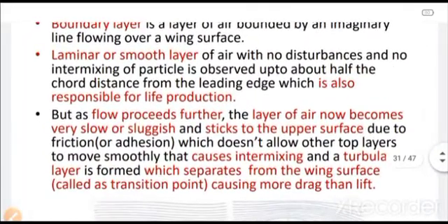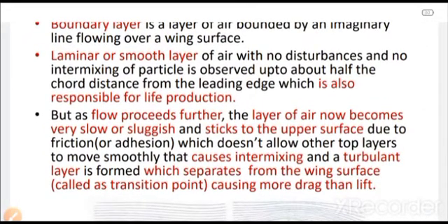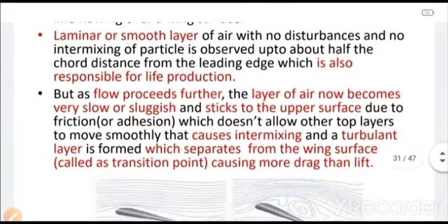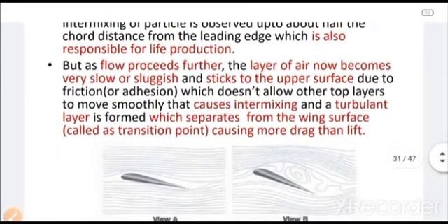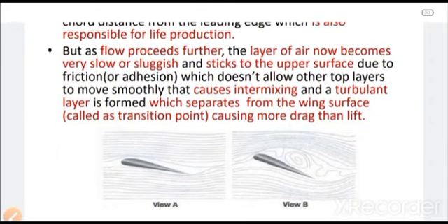so that it does not cause so many disturbances. Laminar or smooth layers of air with no disturbances or intermixing of particles are observed up to about half the chord distance from the leading edge, which is also responsible for lift production. But as the flow proceeds further, the layer of air becomes very slow or sluggish, okay, and that particular layer of air sticks to the upper surface due to friction or adhesion, which is an adhesive force, a sticking force, just like gum. So the air molecules stick to the surface,